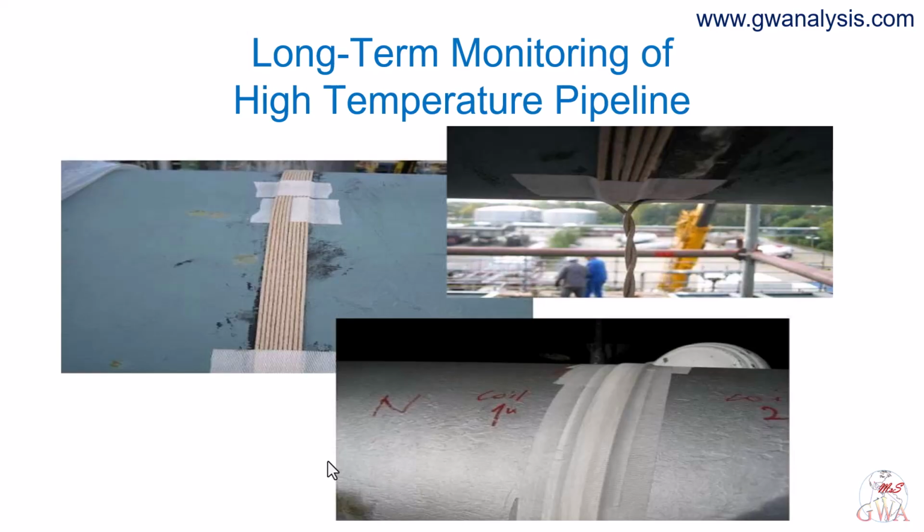There is also a second consideration on a hot line that is specific to monitoring. The velocity of the wave changes with the temperature, because the shear modulus of the steel falls as the steel gets hotter. So if you measure this line in January and again in July, and the process temperature differs, the signals will shift in apparent distance even though nothing on the pipe has changed.